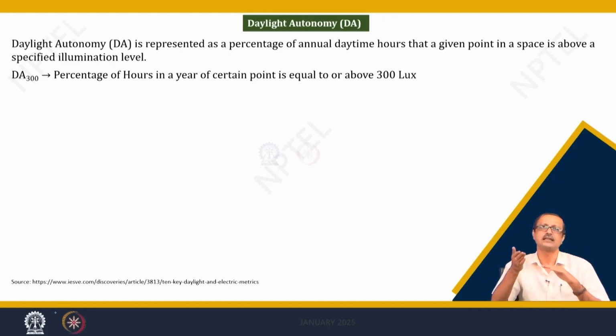You convert that daylight factor to the lux level based on your Eo, the outdoor illuminance. That is the daylight that is going to be available on that working plane for a particular day and a particular hour. So, it is a very static parameter.